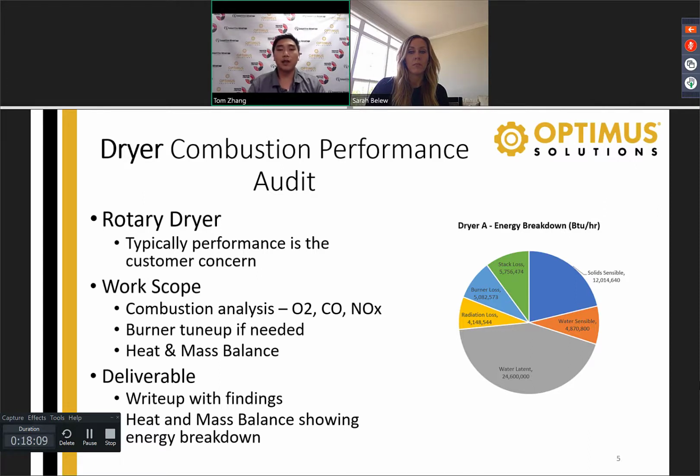At the same time, this is where we can take a look and go, okay, let's say you have X percent of water, 10%. And let's say there's a way you can decrease the water in the feed pile before it enters the dryer, and you can decrease it by 1%. So 10% to 9%. We can run through a scenario and go, okay, how much does it cost you on yours? And typically now it's natural gas, $2, let's say $3 per million BTUs.